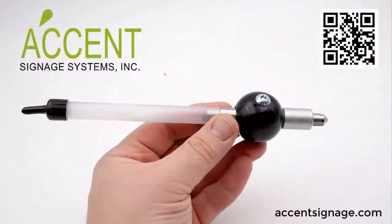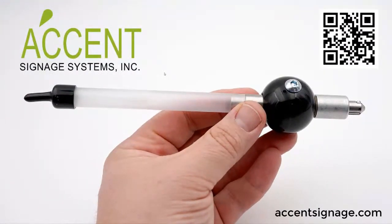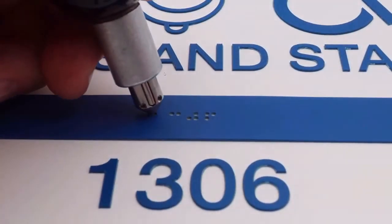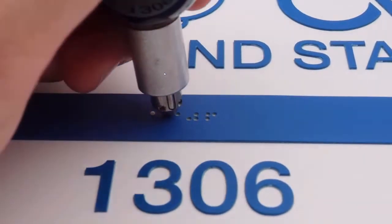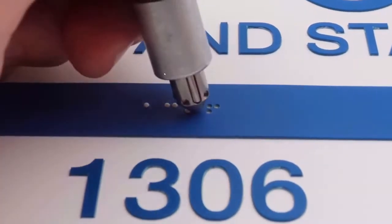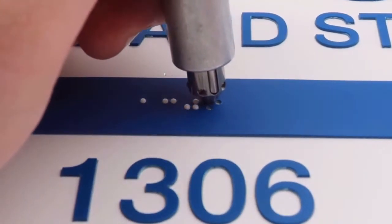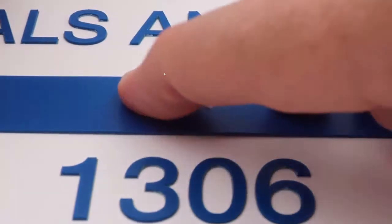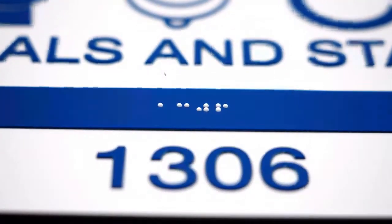Then I'm going to go to our Accent Signage braille raster bead gun. This is a tool that allows you to plunge the little dots, or the braille raster beads, directly into the holes that we laser cut. This is why I place the double-sided tape behind it. You don't have to do that, but it keeps these little balls from falling out in the future. This tool will plunge that little raster bead directly down into the hole so that you have a nice finished result. And here's a nice clear shot that I took of the finished result afterwards.